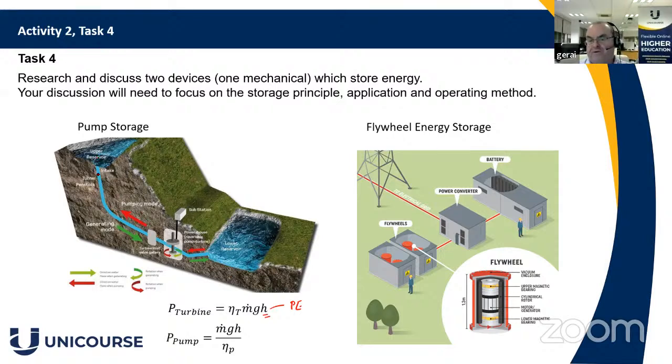However, as you get fluid flowing down the pipe, you get pressure losses in the pipe. So the potential energy will have reduced slightly, and they aim to limit that to about 10%. So the energy comes from potential energy and the mass flow, the quantity of water flowing. And of course, you've got the turbine efficiency to take into account. Typically, these are in excess of 80% efficiency.